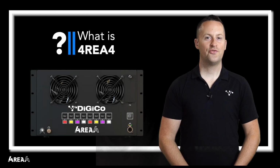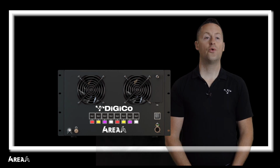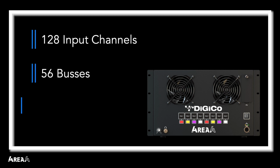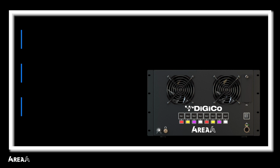Thanks, Molly. So I think the first question we have to ask is, what exactly is the Fourier 4? The Fourier 4 is essentially a mixer in a box. In this box we refer to as the processing engine, and it's where all of the processing happens. It's the brain of the system. This engine is capable of 128 full processing input channels and 56 buses. When we say full processing, this means EQ, filters, dynamics, delay, and effects. All of the buses then have a 4-band parametric EQ, a 28-band graphic EQ, delay, dynamics, and effects.